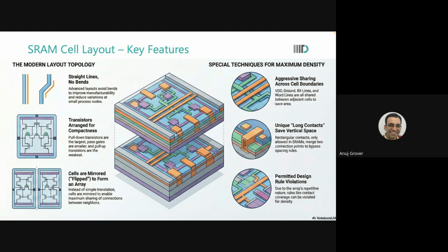In the middle of that piecewise linear, you have the possibility of maximum error. So you need to leave more margins. But for memory cells, because now we know this is the device size, this is the width, this is the length, and this is where the spacing is to be, we actually have exact models. The margins that you need to leave reduce. The Monte Carlo that you do is more accurate.